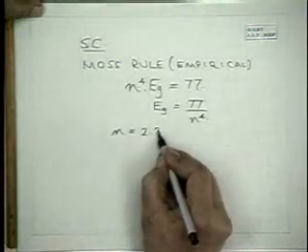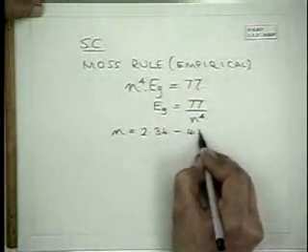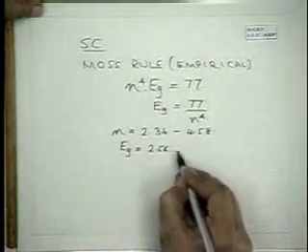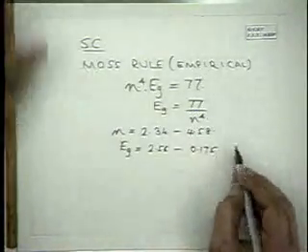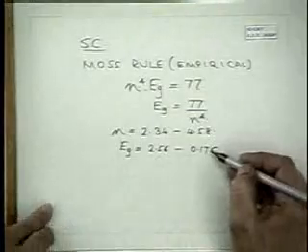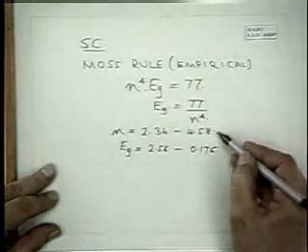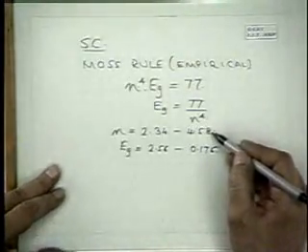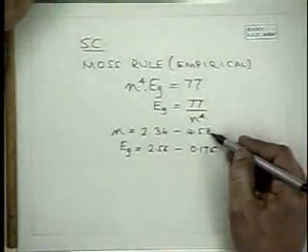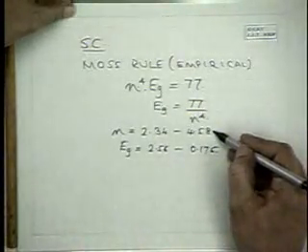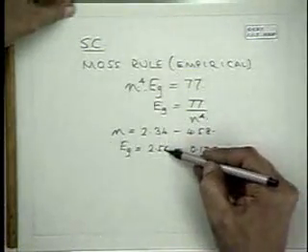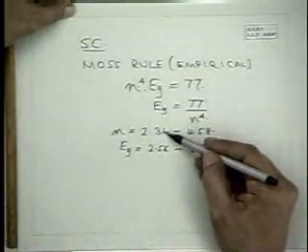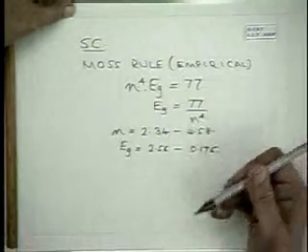This is valid for N going from 2.34 to 4.58, where Eg goes from about 2.56 to 0.175. So if you have a material like indium antimonide having a low band gap, N squared, that is epsilon, is almost equal to N squared, so that would be quite large, of the order of 20. And if the band gap is quite large, then the refractive index is small. This is also important in the case of heterojunctions we've been talking about, gallium arsenide, gallium aluminum arsenide.